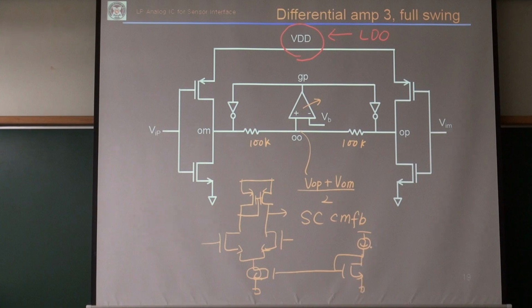The purpose of homework 10 is minimum power. You can reduce this power to set voltage gain of 100. Then you can reduce VDD as much as possible. Then you need a small current here too. For that case, we have two gain stages here.